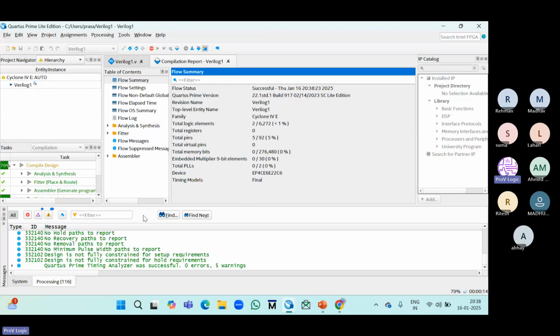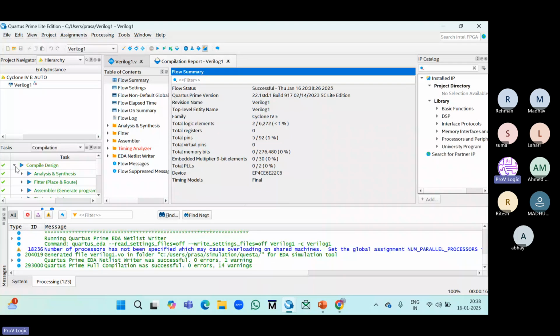So compilation is done. On the left side, if you observe here, there are a lot of options: analysis and synthesis. Our main thing is we need to do only synthesis. Next, filter, placement, routing. These are not our things. In the backend of the PD flow, we do placement, routing, and clock tree analysis. Here, timing analysis, netlist viewer, everything is a backend process. If you install the tools, you can check once. I will show you once here.